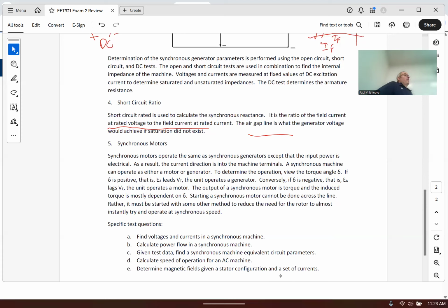And then I started reading about it, and I learned I need to have this thing spinning, because the field was rotating so fast, at whatever the speed was, 1800 RPM, that this big hunk of mechanical whatever just couldn't latch on. It couldn't accelerate. So to start it, I had to do some other things. One thing you can do is start it with a variable frequency drive, because if you run at 1 hertz versus 60 hertz, that's 1/60th of the speed, and it can probably catch up.